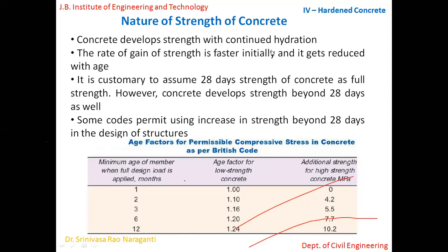But in reality, what happens is the concrete continues to gain strength even after 28 days of its age. But its value is not phenomenal if we talk about regular mixtures, regular ingredients, like if you're using only cement, fine aggregate, coarse aggregate, and water, and to some extent some admixtures. Then after 28 days, we don't see a substantial increase in the strength. However, there will be some increase in the strength if you use normal ingredients. But we assume that concrete gains complete strength in 28 days itself.